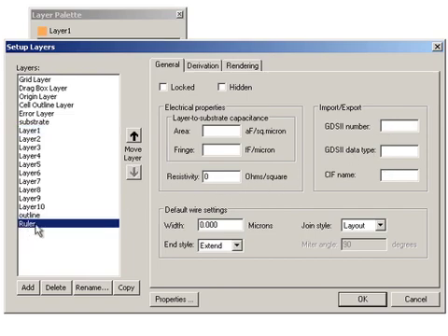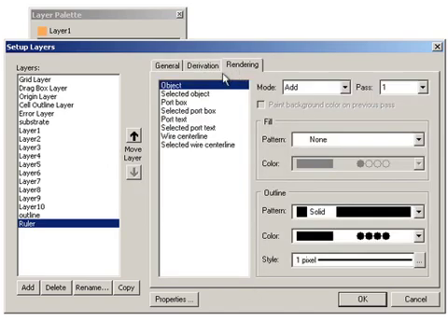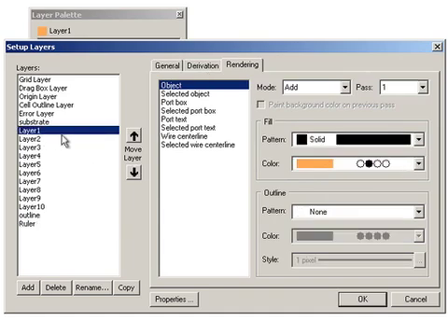So as we see, the outline and the ruler layers do not have one. And one thing you cannot do is draw on an arbitrary layer and then choose some random number and punch it in there and hope that that's going to be exported. That will not work. So basically you just have to make sure that you choose an appropriate layer, and then you can continue drawing in that way. Some of the other tabs here have some more advanced features. If you like, you can play with them.